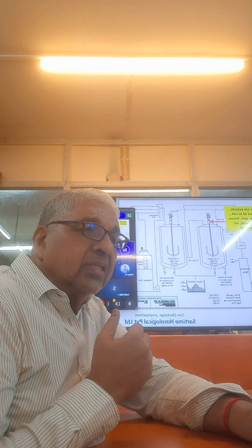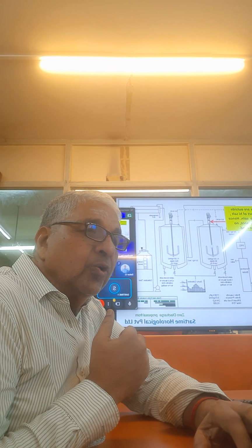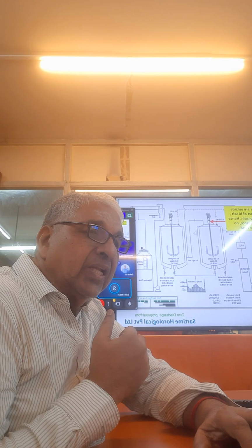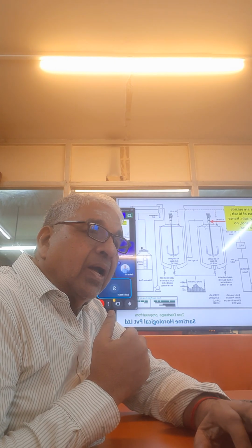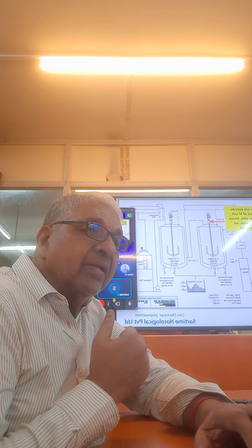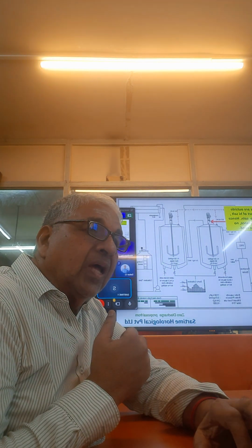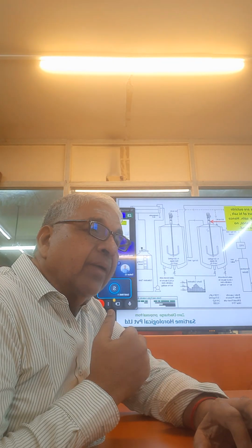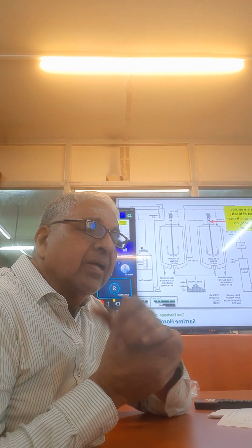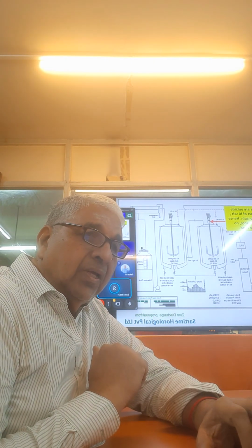Okay, sure. This is our type of evaporator, where there is no tube. It's a vessel in SS316L, and you are stirring it, and there is a steam jacket outside. And in the normal evaporator, the main failure happens in the circulation of the hot salt water.